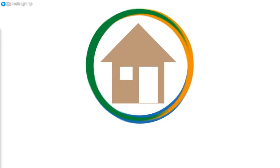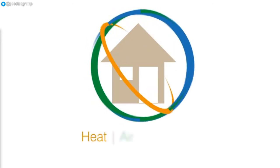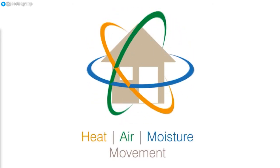While successive government strategies have focused on reducing energy use in older buildings, the wider implications of this have not always been fully considered. Designers must therefore have a good understanding of the materials being used in both the upgrade process and the original construction. By recognising that refurbishment cannot simply upgrade thermal insulation without also addressing the balance of moisture movement and air leakage, we can ensure the most optimal upgrade solutions are achieved.